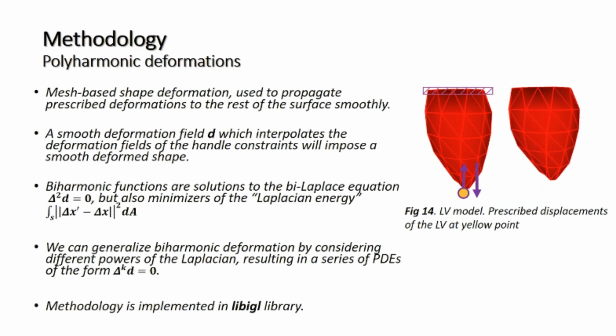solution to a linear partial differential equation. There are many flavors of these techniques, but prototypical subsets are those that consider solutions to the bi-Laplace equation, that is, biharmonic function. This fourth-order PDE provides sufficient flexibility in boundary conditions to ensure continuity at handle constraints in the limit under refinement. A smooth deformation field D, which interpolates the deformation fields of the handle constraints, will impose a smooth deformed shape. Naturally, we consider biharmonic deformation fields subject to some handle constraints.